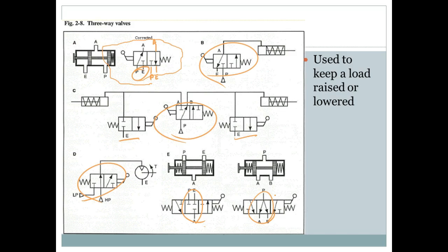So when you turn it on, it'll shift everything to what it considers its initial position. If you went over there and looked at the manufacturing line, every one of them has a reset. You flip the reset. Well, what does that do? That shifts all your actuators back to their start position. All those two-way valves, if it has a spring on it, then your normal position is whichever way the spring is pushing. So those are drawn wrong.